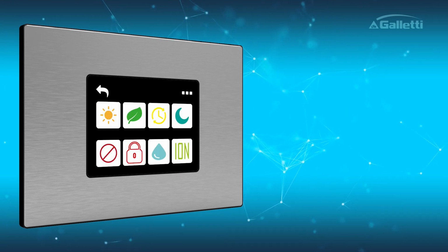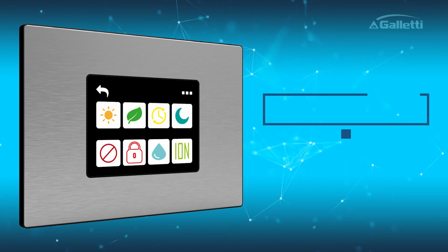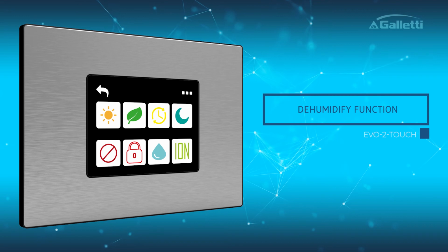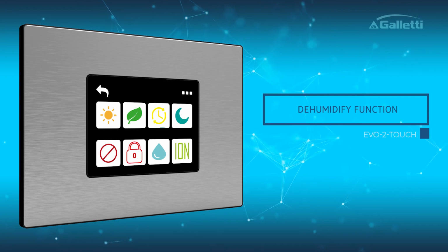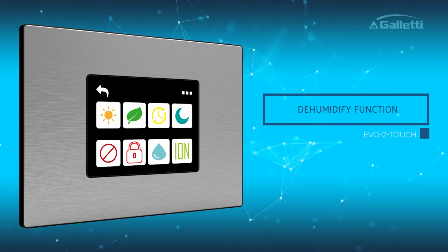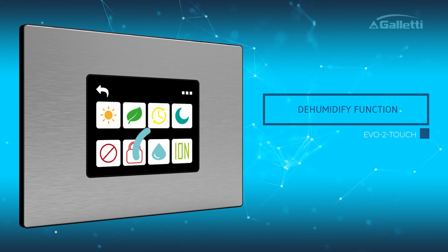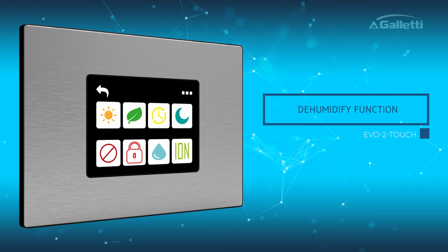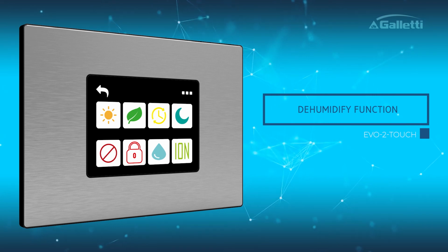The EVO-2-TOUCH display shows an internal humidity probe. Therefore, it is always possible to enable the dehumidification function. If the dehumidification function, which can only be used in the cooling mode, is enabled in the user menu, the unit will operate with the aim of reducing the humidity in the room.